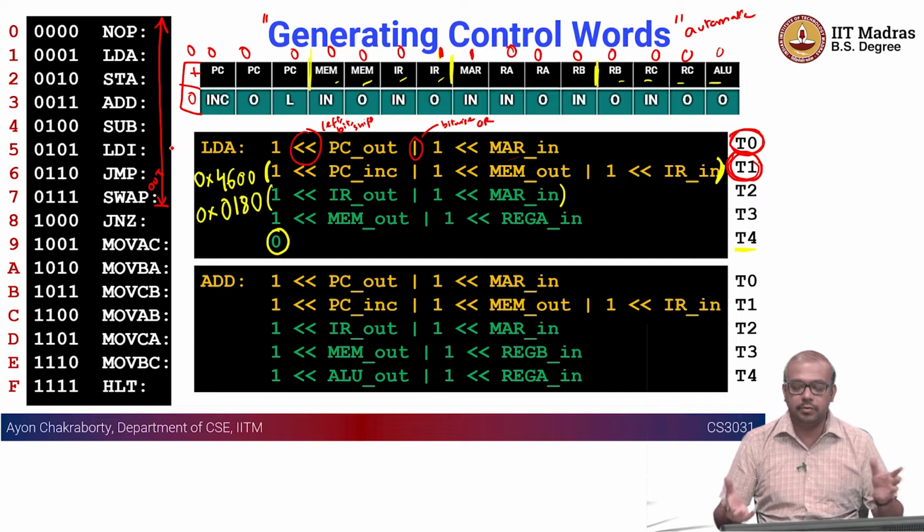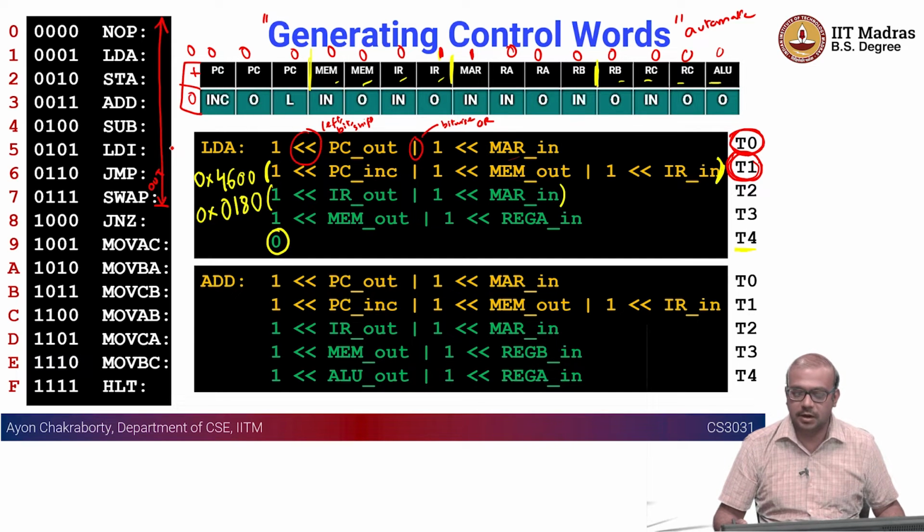So by now you know how exactly this control logic works. We take a few bits from the opcode, which tells which instruction it is going to be. We take the bits from the T state counter, and then use that as an address for our control ROM logic. Whatever data is at that address is our control word, or our microinstruction.